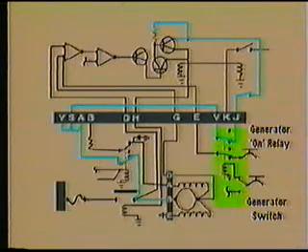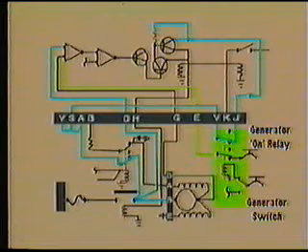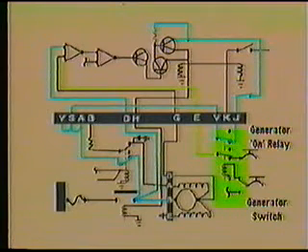Power now travels from the B lead, through the control panel, through the closed contacts of the on relay, and back into the regulator panel. This power is also routed to the first operational amplifier, which now compares the generator voltage and the bus voltage. If all these voltage levels are correct, an output will be provided.